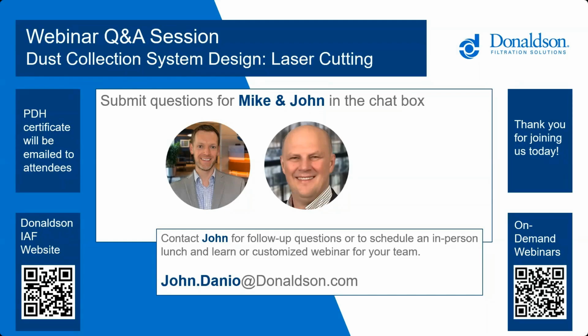So, if you know that a customer has, for example, a 20 kilowatt laser that they want, and they're always going to be cutting, let's say, 1/2 inch thick material, and they're running 24/7 versus 8-hour shifts, you're definitely going to want to size the AMR more conservatively. So think of the thicker the material, the more they're cutting, the more media you're going to want to have present on the system.